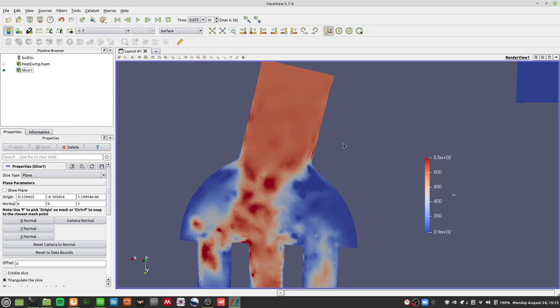So what are we seeing here? Try to visualize. Air is flowing into this heat exchanger, but somehow over here, for some reason, there is some temperature increase. Now what's the reason for a possible temperature increase? Thermodynamically speaking, it's probably because the pressure at that region suddenly increases and does work on the air.